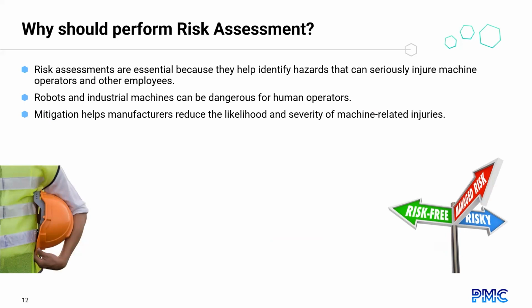So imagine the operator working in an area with a vast amount of welding robots and other industrial equipment, for example. So this can be very, very dangerous for the operator. That's why the risk assessment is so important, because it will help us reduce the likelihood and the severity of machine-related injuries by implementing control measures, protecting all the operators in their workplace.